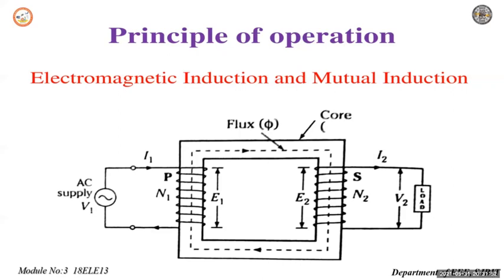Practically, winding resistance is very small. For DC, the inductive reactance XL is 0 as DC has no frequency. So, the total impedance of the winding itself is very low for DC. Thus, the winding will draw a very high current if DC supply is given to it.